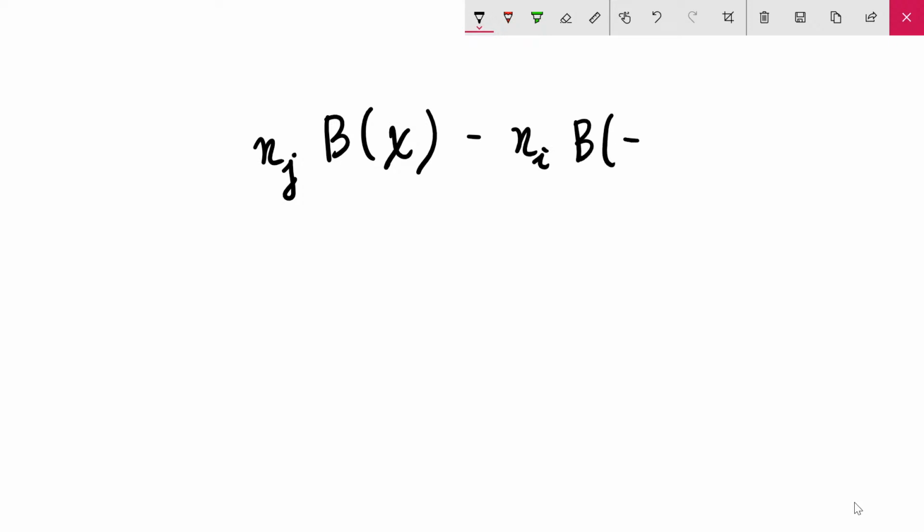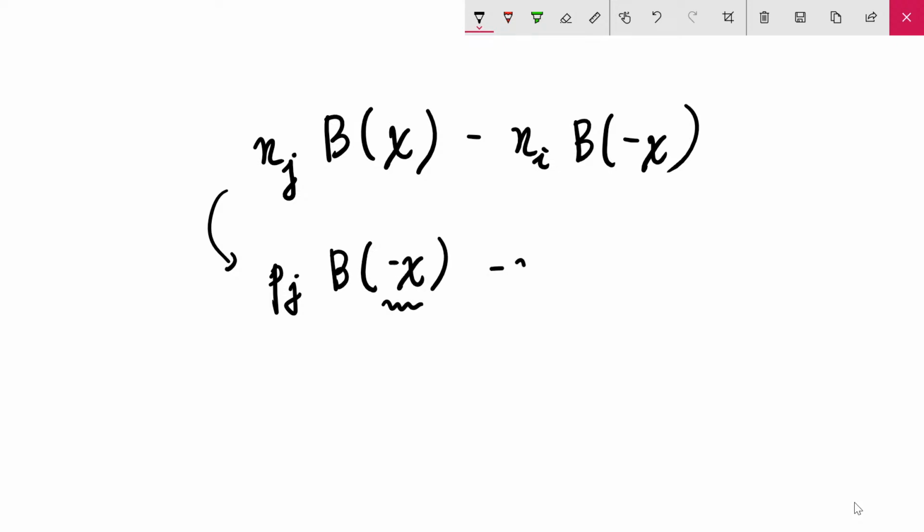However, frankly speaking, I just remember that sign. So in the case of electrons, yes, I just remember this one, J positive minus Ni Bernoulli. Yes, that is the thing I remember. Also, I do not explicitly remember the form for holes, but instead, I just remember that the input argument for our Bernoulli function should be inverted. So inverted for our hole current density. So that's it for remembering all these complicated notations.